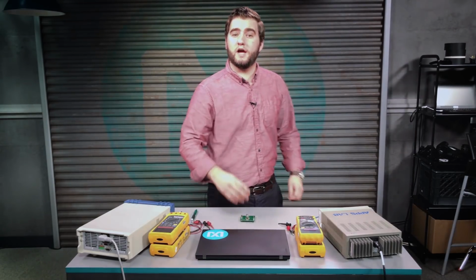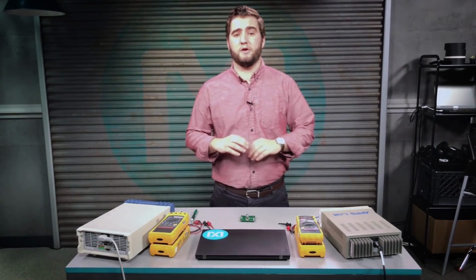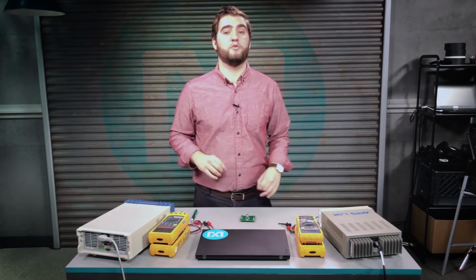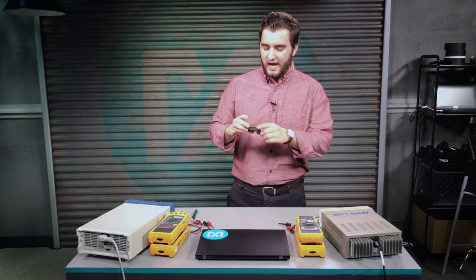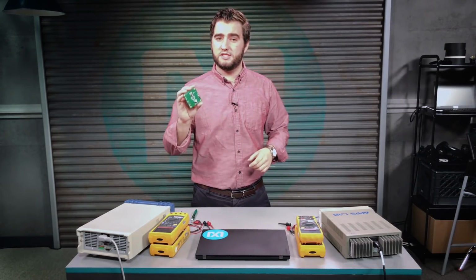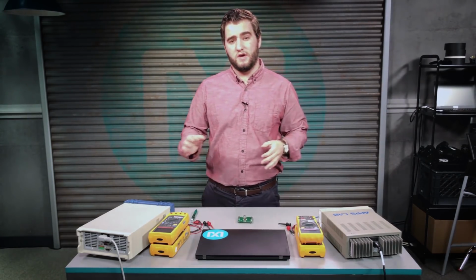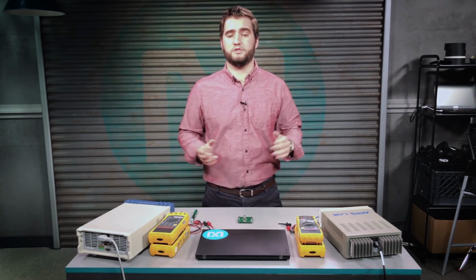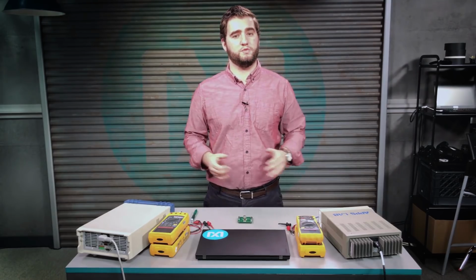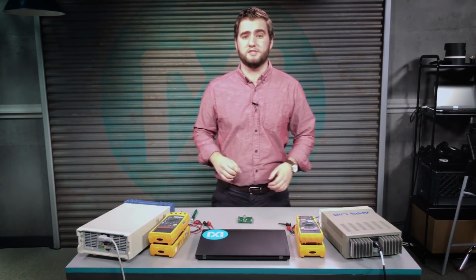Now if you're thinking what I'm thinking, the EESIM tool is pretty slick. I was able to design a power supply and simulate it in a number of minutes. But how reliable are those simulations? Well, I have the MAX17506 EV kit right in front of me. It's configured for 12 volts in, 5 volts out, 5 amps out with a 450 kilohertz switching frequency, exactly how our simulation was configured. Let's take some efficiency measurements and see how the hardware and the simulations compare.